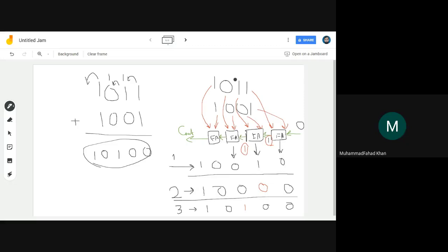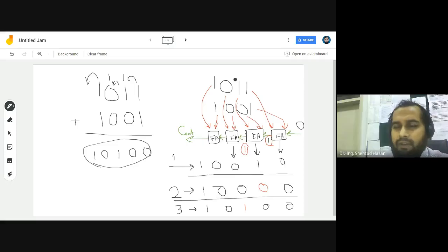Every time all the full adders would be computing their answers? Yes, yes, yes, because all of them are there. There are four full adders, and they are always going. In any combinational circuit, you cannot prevent it from giving any output. In a sequential circuit, you have registers, and these registers are operated on a clock, right? So you can manage that input change if you manage the clock.